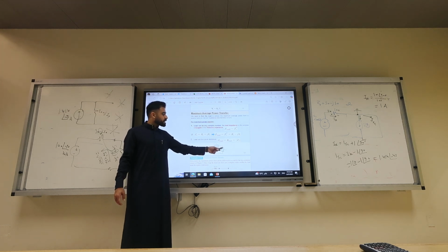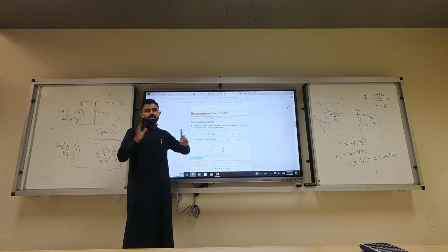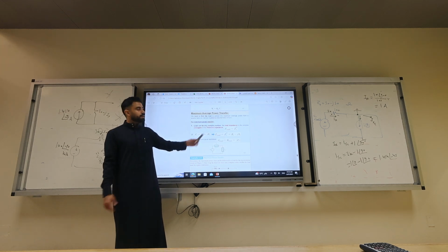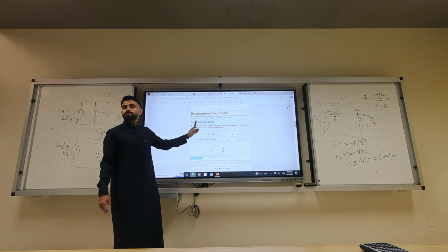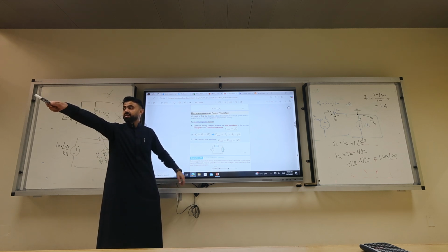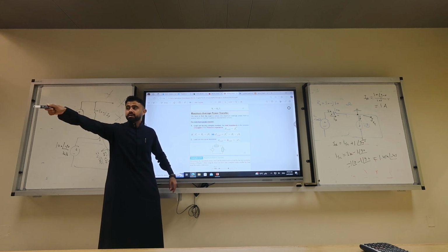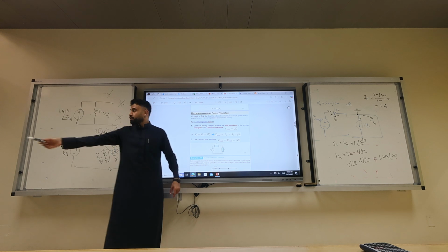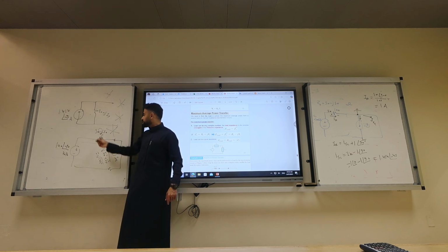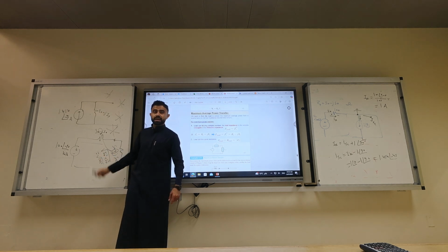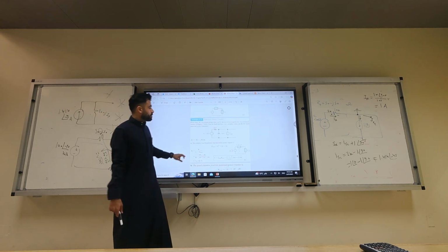So that box can be only R or R plus either capacitor or inductor depending on Z Thévenin. Hatem, if I bring the question in the test, can you calculate Z Thévenin? Can you calculate the maximum power? Z Thévenin conjugate. What's the trick with the conjugate? You replace the minus J with plus J. If this was plus, this will be minus J. Get it? Okay, you can leave.